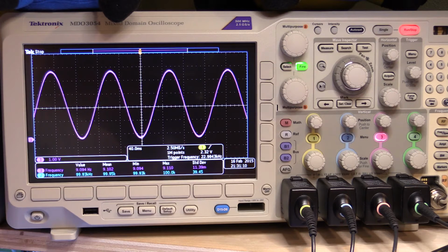Now we probably could increase maybe the I2C bus clock speed, because the chip will handle up to 3.4 meg. I haven't tried changing that frequency to see how well it will do, but that's an option. But anyway, that's not the purpose of this little video. What I wanted to show is the fact that we can quite easily now set up an analog to digital converter, a digital to analog converter, to significantly increase the resolution of the Arduino Uno.